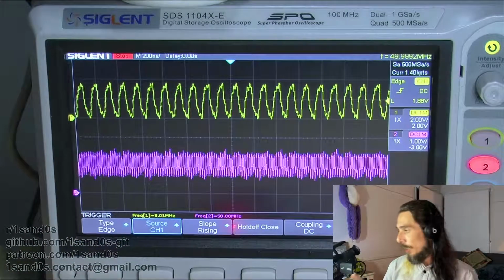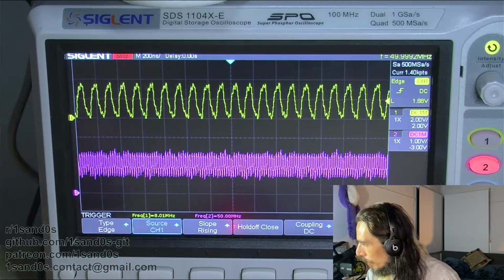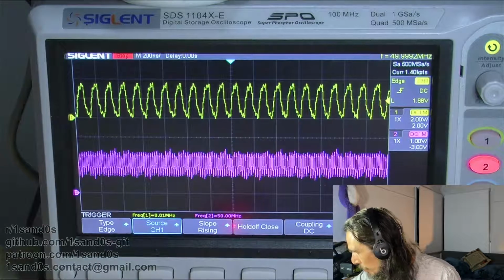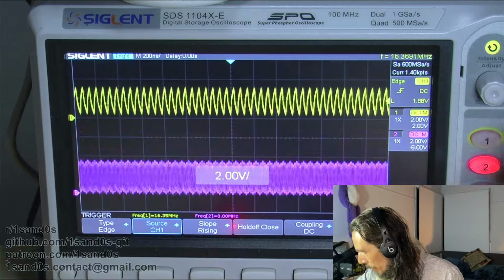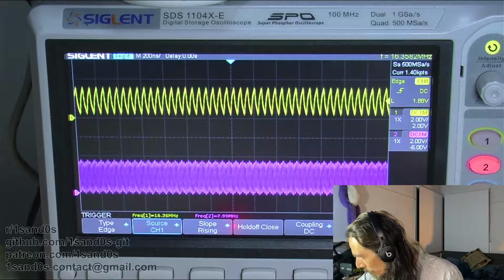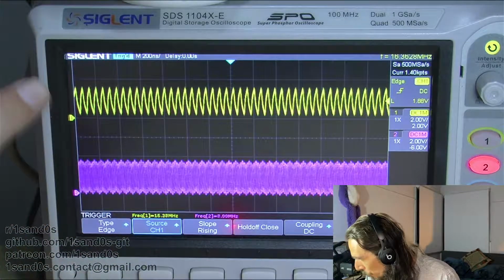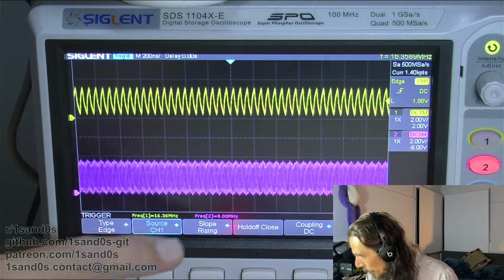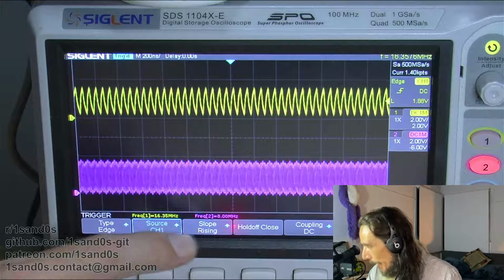So I've also got the oscilloscope just measuring the frequencies of the two different clocks. That was from a previous run. Let's just adjust our settings here. Make both of these about the same. And we can see it's currently measuring our top clock, which is our high-speed internal, at just over 16 megahertz. And it's measuring our high-speed external at pretty much bang on 8 megahertz.